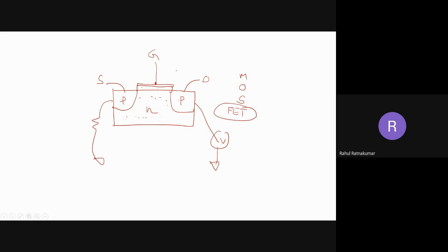So I'll give a voltage here, a plus voltage. I give a plus voltage here, VG or VGS. This is based on the gate, so VGS. I call it VGS with respect to ground, the source, right? So I give a voltage VGS. That means this is a positive voltage. First of all, it repels. Okay, this is an N channel, so I should give a negative voltage here.